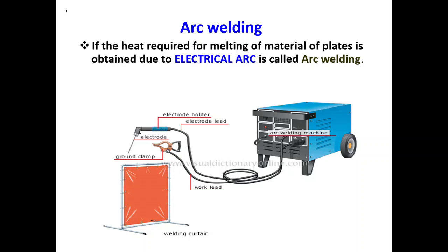Next is the flux. Flux is a substance that prevents the formation of oxides and other unwanted contaminants. The unwanted substances dissolve in the flux and float on the molten metal pool, so they can be removed easily after solidification. This is known as slag removal. Fluxes are also useful for providing a protective atmosphere for welding, stabilization of the arc, and reduction of spatter.